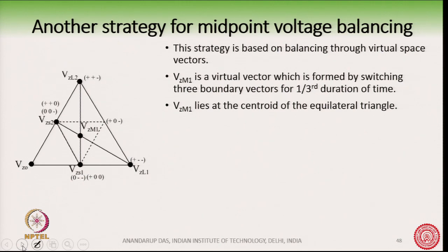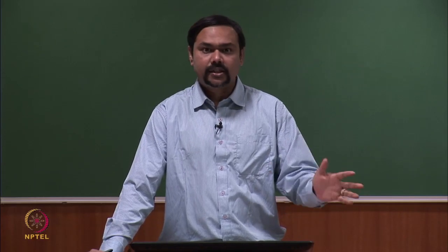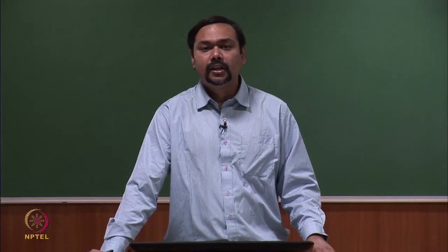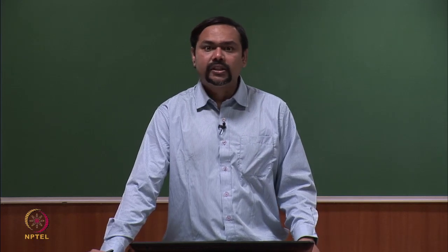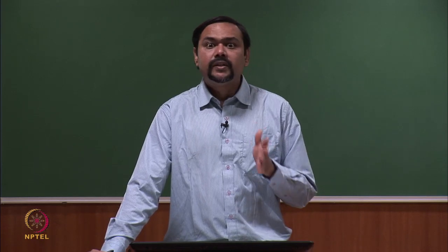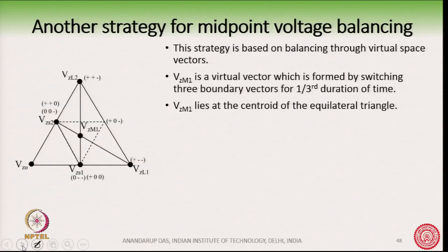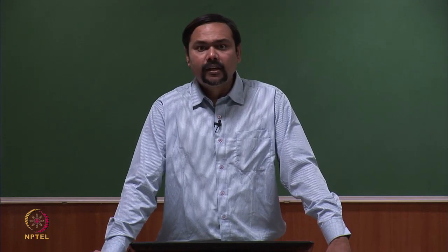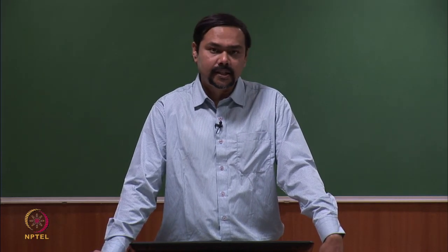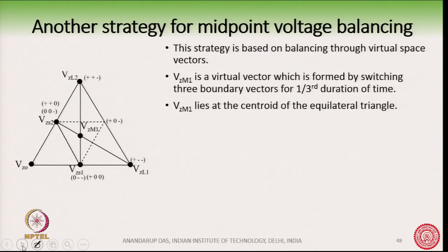We have just seen one technique which has certain limitations, in particular at high modulation index. Now, we will see a second strategy which uses the virtual space vector concept. It came in IEEE Power Electronics Letters, probably in 2004. This is a very interesting technique which we will see for balancing the neutral point voltage.